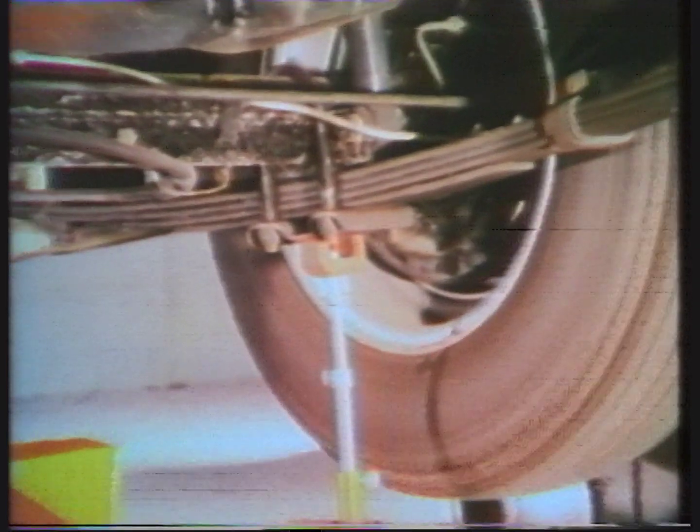A typical example would be vibration in hand wheel, noticeable at 35 to 40 miles per hour and at all speeds above. Vibration at front of car. This is clearly the first condition discussed and calls for further careful attention to front wheel and tire runout and rebalancing. Remember that tire and wheel runout are responsible for a proportion of normal balancing jobs and for a high proportion of the remaining difficult cases.